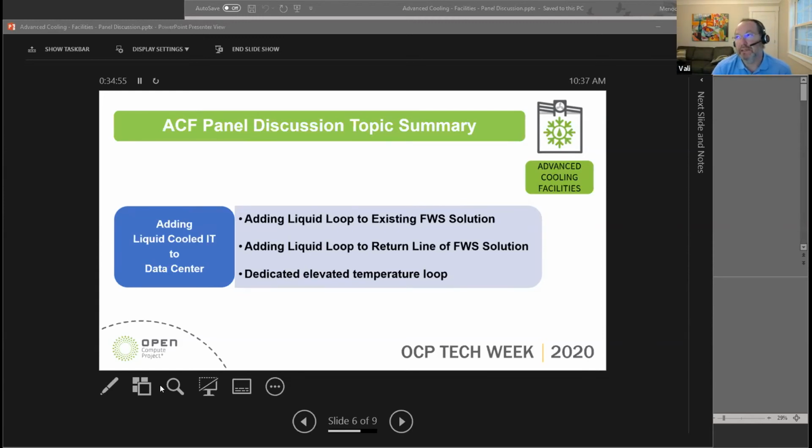How about 60? With some higher workloads, it's very possible that at those continued high processing conditions, it may start throttling a bit to protect itself. The temperature at which throttling occurs may be upwards of 80, 90, or even 100 C before it actually starts doing that.